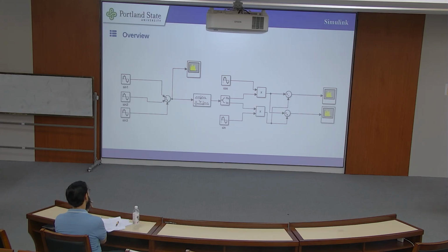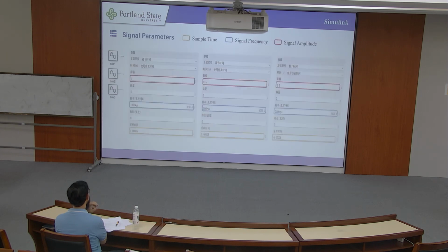We multiply the real part with the carrier signal cosine, and multiply the imaginary part with the sine signal. By subtracting the sine branch from the cosine branch, we get the USB signal, and by summing the two signals, we get the LSB signal.